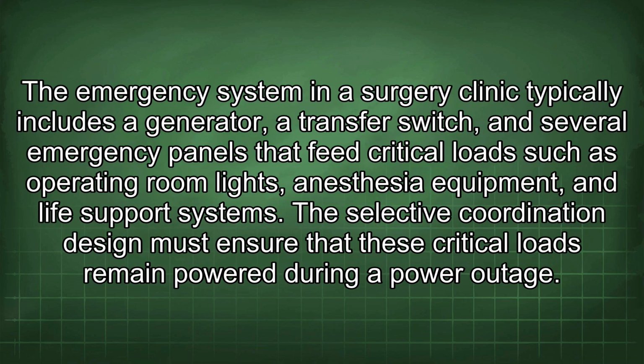The emergency system in a surgery clinic typically includes a generator, a transfer switch, and several emergency panels that feed critical loads such as operating room lights, anesthesia equipment, and life support systems. The selective coordination design must ensure that these critical loads remain powered during a power outage.